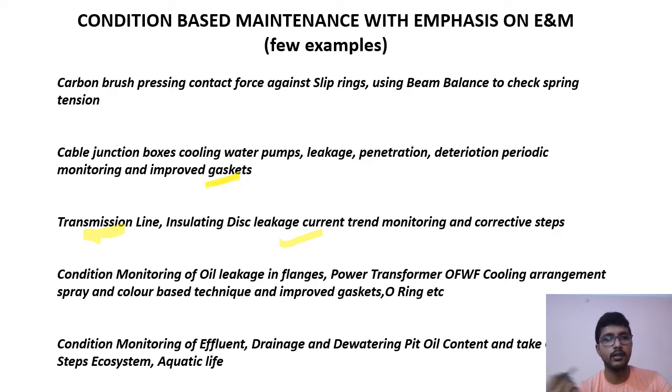We need to work on the switchgears. We need to work on the high voltage insulators and maybe hotline washing, hotline cleaning. And if shutdown is possible, we take a plant shutdown and clean all those switchgears, insulation parts, and whatever way we can ensure that the creepage length is okay, right?